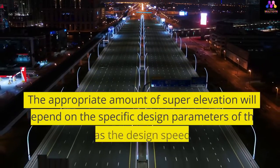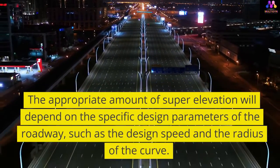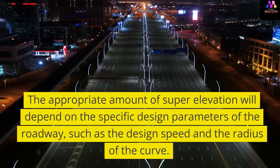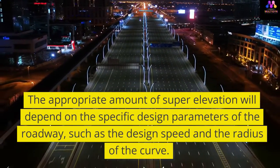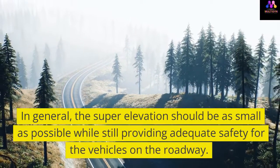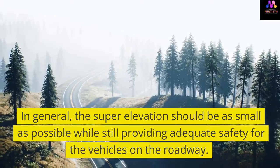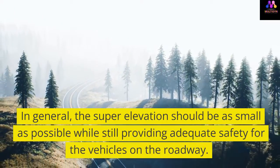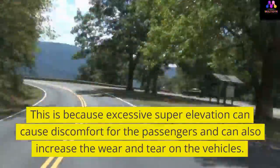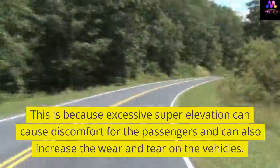The appropriate amount of superelevation will depend on the specific design parameters of the roadway, such as the design speed and the radius of the curve. In general, the superelevation should be as small as possible while still providing adequate safety for the vehicles on the roadway. This is because excessive superelevation can cause discomfort for the passengers and can also increase the wear and tear